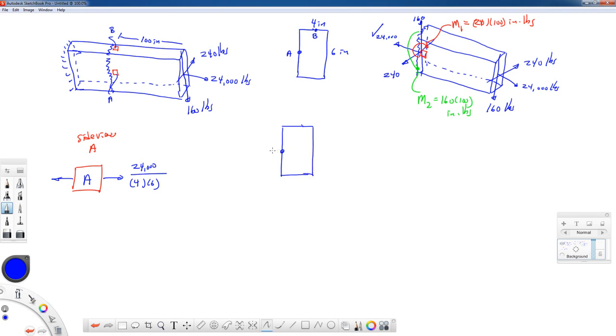Okay, so point A is right here on the side, and I find it convenient to draw in the bending axis. So it's putting the top in tension and the bottom in compression. It's bending about this line. Point A is on the neutral axis for that bending moment. My over I, that y distance is 0. So M2 does not cause stress at A. Let's just make a note of that. Alright, so we're done with that one.